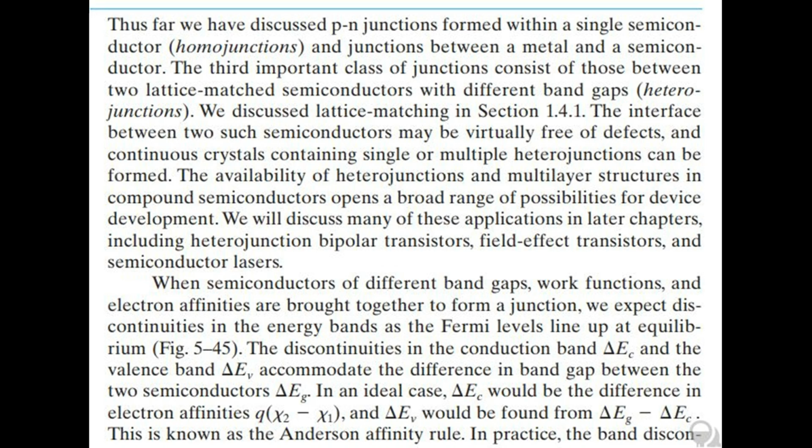Figure 5.44. Fermi level pinning by interface states in compound semiconductors. A. EF is pinned near EC, 0.8 electron volts below it in n-type gallium arsenide, regardless of the choice of metal. B. EF is pinned above EC in n-type indium arsenide, providing an excellent ohmic contact.